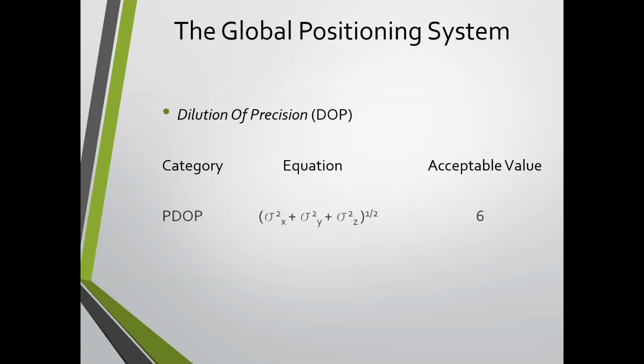Basically, this is just a position. It's kind of a delta X, delta Y, delta Z kind of thing. And notice that's just, again, a triple. Acceptable value by this, when I wrote this, is 6. You really probably want to be lower than that by today's standards. HDOP, we were looking at 3. VDOP 5, and I don't even think they have geometric position.